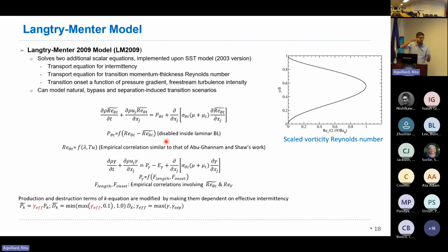That information will, through this transport equation, diffuse into the boundary layer. And within the boundary layer at each point, you will then have the critical Reynolds number at which transition is supposed to happen. Once that information is there, it is then used in this intermittency equation, which is active in the boundary layer. And you'll say, oh, my current estimate for boundary layer momentum thickness is more than the critical number. So I'm going to turn on intermittency, increase the production, and then turn on the turbulence term. So you'll increase the gamma value. And this gamma is like the same intermittency function which we are using in the stability analysis, but with slightly different meaning. So this will essentially multiply your production term of your turbulence term, and then turn on the turbulence production in your RANS equations.